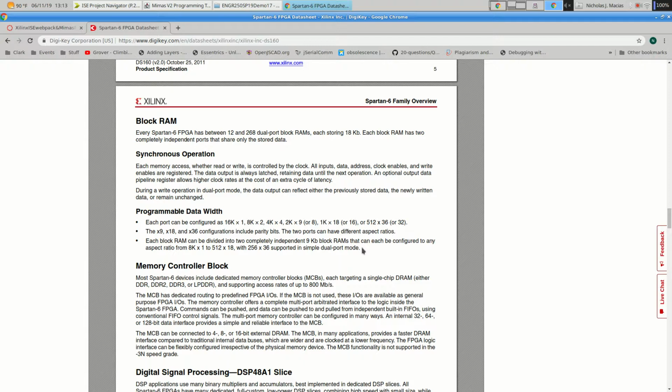Usually a few flip-flops on the output side, some feedback so that we can make sequential circuits out of these. And then in between each of these logic blocks, whole bunch of wires. And by setting multiplexers, we can connect outputs of one block to inputs of another block. And we can basically control the routing of inputs and outputs throughout the FPGA by just setting up the inputs to multiplexers. And that's what most of the space inside these devices is, just wiring, just routing to connect things together. And part of what the software is doing is figuring out the optimal way to route it in terms of speed and power and so on and so forth.